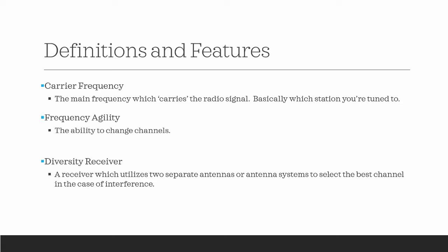The next thing we want to talk about is frequency agility. This is an important feature to note while you're speccing out wireless systems. On the lower end, without naming any manufacturers, there are a handful of wireless microphone systems that are designed and intended for prosumer uses, basement karaoke, that sort of thing. They're fixed frequency, which effectively means that if you experience interference on a channel, there's no way for you to change channels and get around it. So basically, if you're tuned to 534.600 or whatever, that's what you're going to be stuck with.